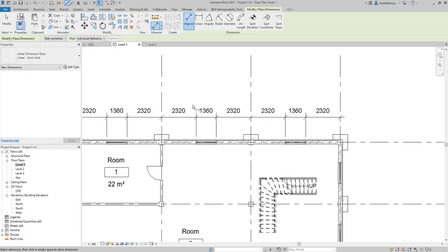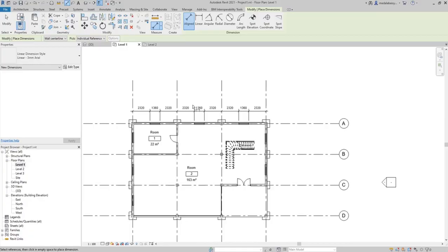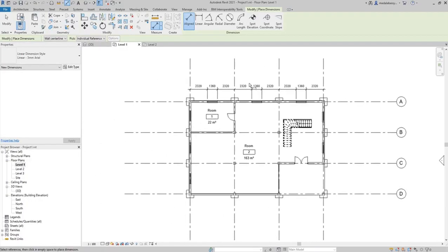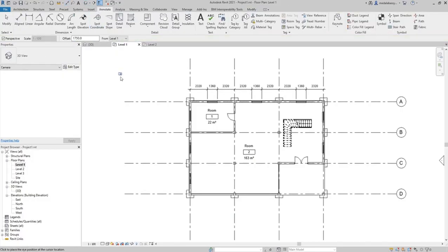I'll move to section 16, creating camera views. So I'll just center the plan a little bit. To create a camera view, you need the camera, of course. So I'll just go to this window and then select a camera here, and I will place it somewhere, I guess as mentioned in the tutorial, somewhere here, and then set the view to around here, I guess.